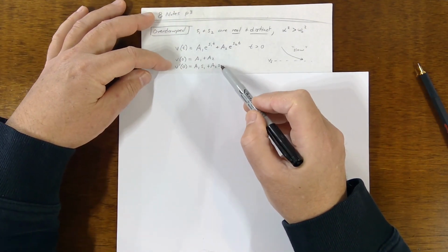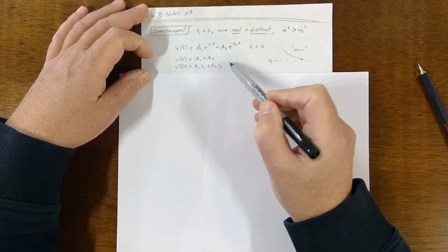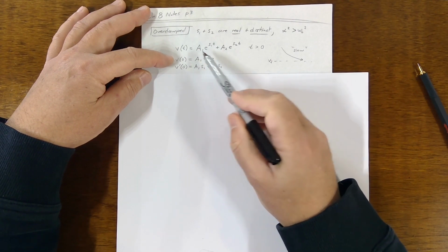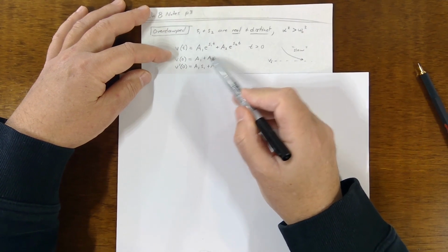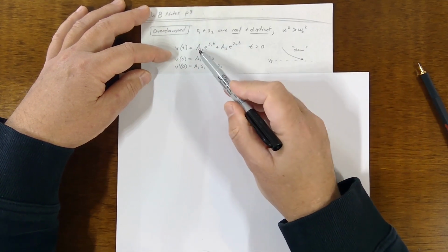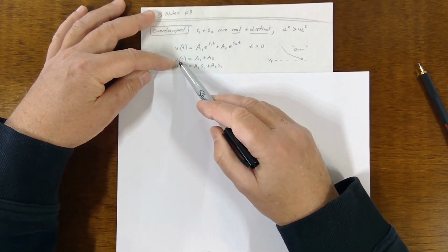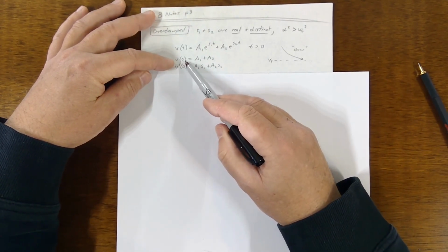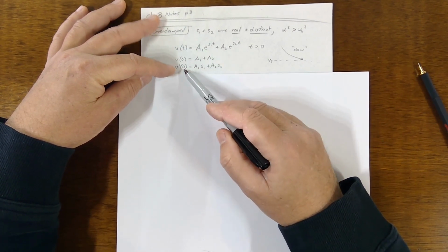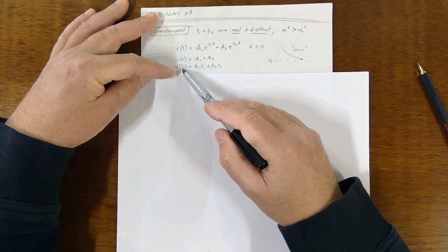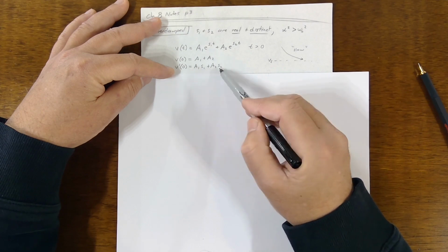And we have these additional two equations that are true. We're skipping all the derivation, but these two equations are useful for determining usually the constants. Well, the thing is, you're going to have knowns and you're going to have unknowns. Some of these things will be known, and then you'll solve for the unknowns. But anyway, the initial voltage in the system here is the sum of these two constants, and the initial change in the voltage, or V prime at 0, is this thing.